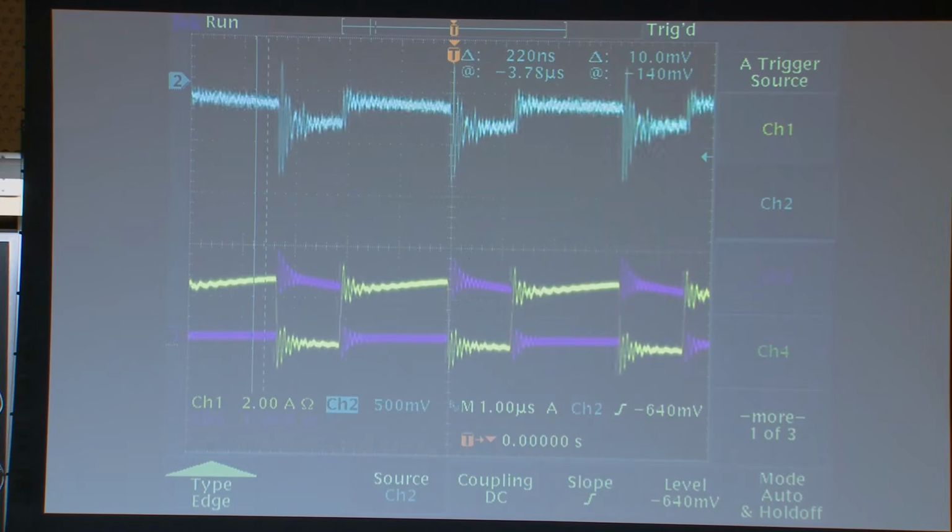So you have a purely AC voltage across the transformer, which is hard to see because it looks like there's a little offset. But it's supposed to reflect that you have a positive voltage in one part of the cycle and negative voltage in the other part of the cycle. So when blue is high, the magnetizing current's rising. When blue is low, the magnetizing current's falling.